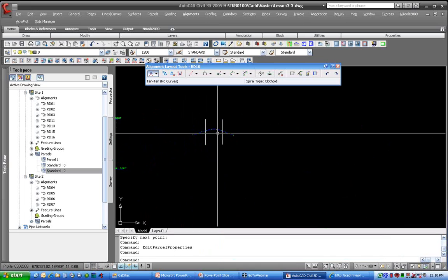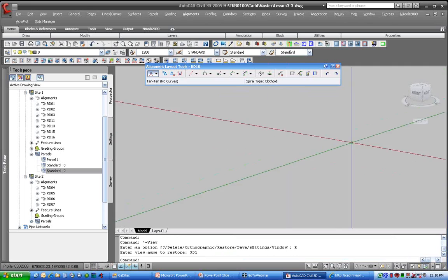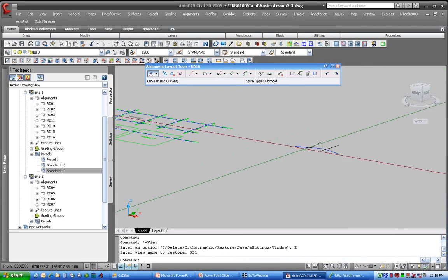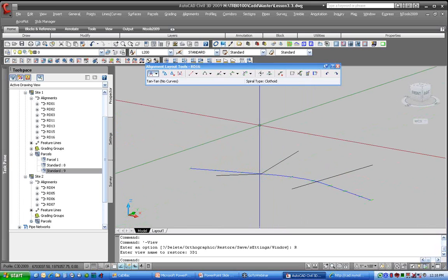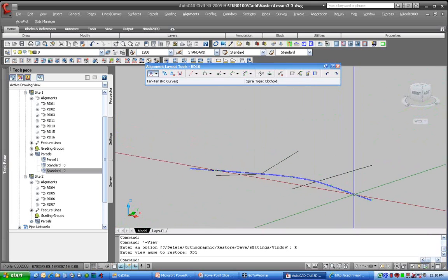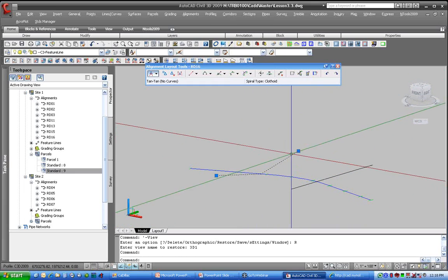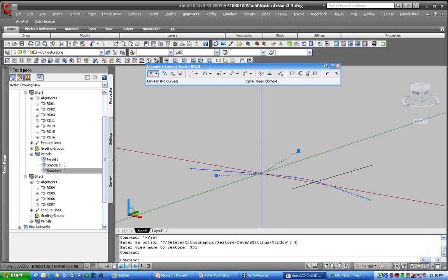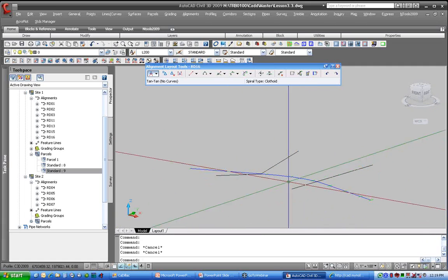All right, last one here, this is my feature lines, and let me go to a 3D view here. Find my model real quick. What you have is I have an alignment, and I'm going to split my viewport, but I'm not going to modify this, but I've drawn the alignment through here. This feature line is on the same site, and you'll see that it automatically snapped it down, put in the split point where it intersects the alignment, whereas this feature line is on a different site, and those did not interact with each other.